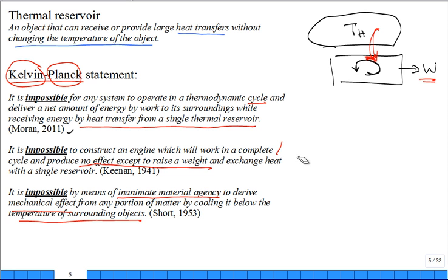To have a good heat engine, you must have a sink. You must have a lower temperature, or what we call a cold thermal reservoir, and you want to convert as much of this QH into W, but you will have to, it's a restriction, dump some QC to a lower temperature body. You cannot have a heat engine running in a cycle operating only with one heat source, no heat sink. You have to throw some of that heat energy away, and that bugs people. It bugs people in the media, it bugs me, because we don't like limitations. We want to be able to convert all of that energy into the most useful form of energy. Well, you can't convert all that heat energy into work.